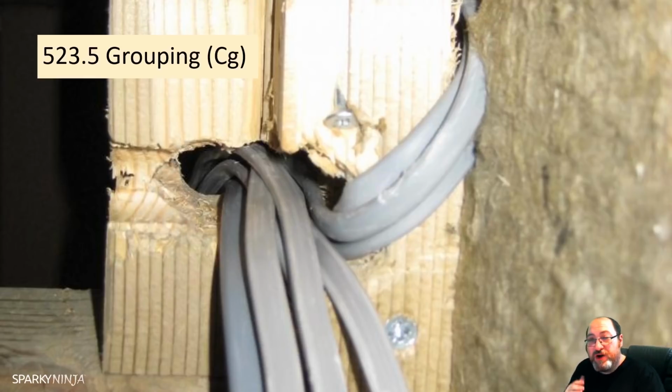Now this table requires understanding of the reference methods. We've talked about reference methods A, B, C, D, all of those. So when you're looking at this table, you have your items 1, 2, 3, 4, then arrangements of cables that are touching. So it's only if the cables are touching. Now this could be they're touching, such as here. That's fairly obvious. But it could be one cable that's surface clipped next to another, but then just this side, this part of the cable is touching.